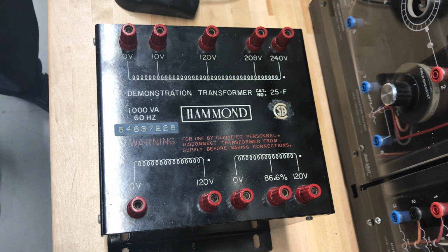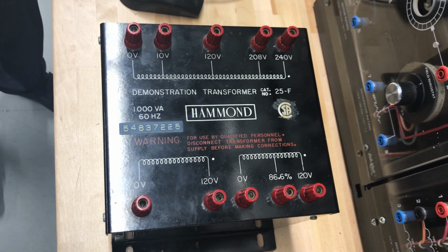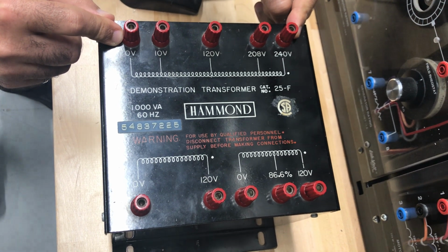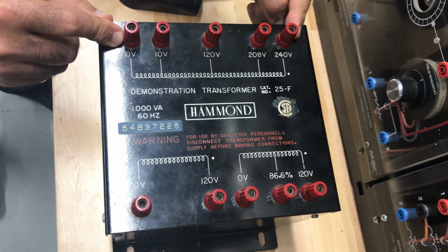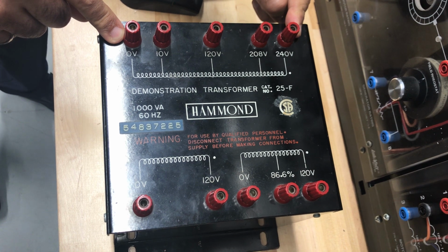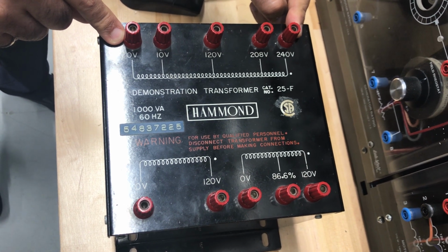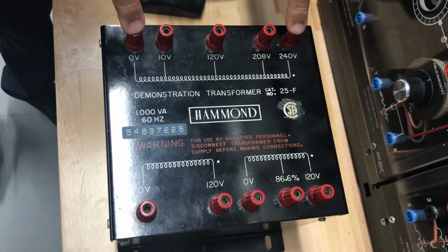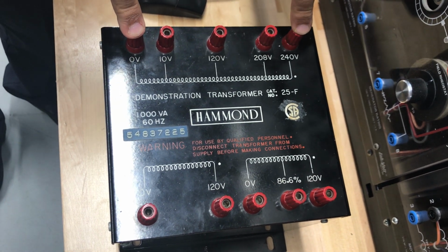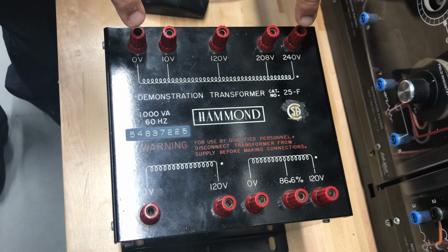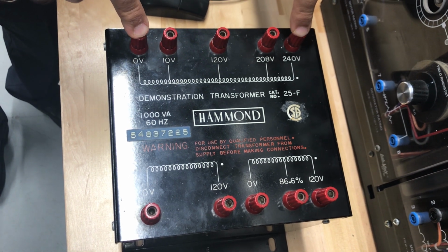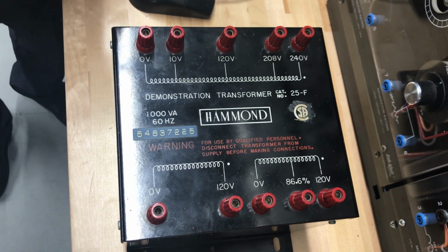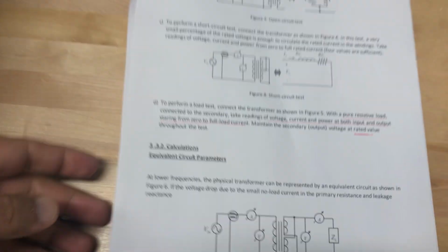So I'm expecting that the current will be high because the current based on that winding will be equal to V divided by Z. In our case, for DC, we don't have Z, we have only R, which is R1. That's why I will be careful while I'm applying voltage here, which is DC volt, and I will measure the current and the corresponding voltage and divide them to find R1. Like what we did here.